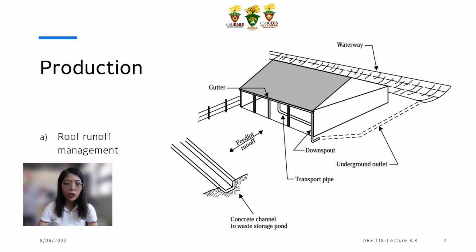For production, components that affect the volume and consistency of the agricultural waste produced are included in the production function. Roof gutters and downspouts and diversions to exclude clean water from areas of waste are examples of components that reduce the volume of waste material that needs to be managed. Fences and walls that facilitate the collection of waste confine the cattle, and thus increase the volume, right?